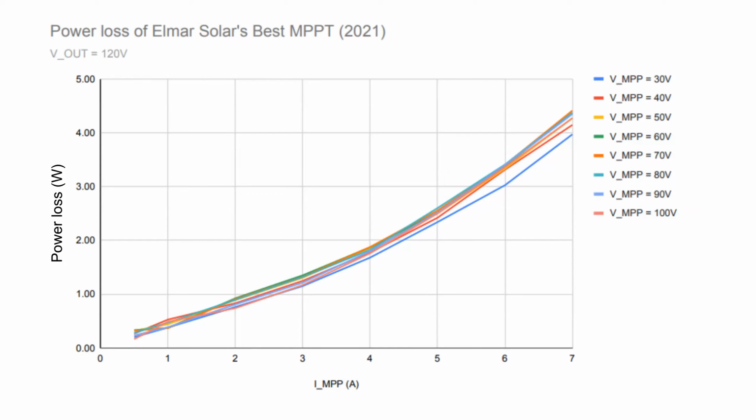If you connect double the amount of solar cells, you have a similar amount of losses. So connecting double the amount of solar cells to a maximum power point tracker gives you approximately the same losses, so the losses in percent get cut in half. So maximum power point wise, you would like to connect as many solar cells to an MPPT as possible, because then you get the highest efficiency. But loss wise from grouping, you would not want to connect more cells in series, because then you get the grouping issues. So there are other solutions as well.